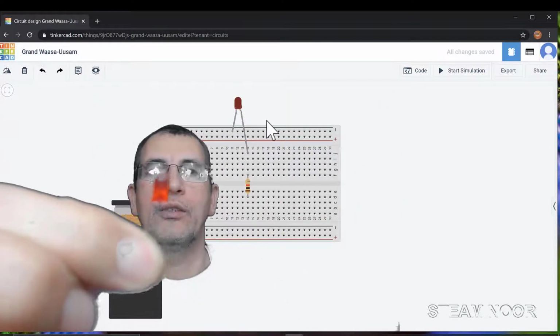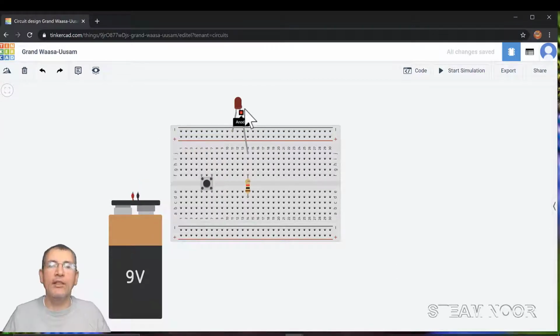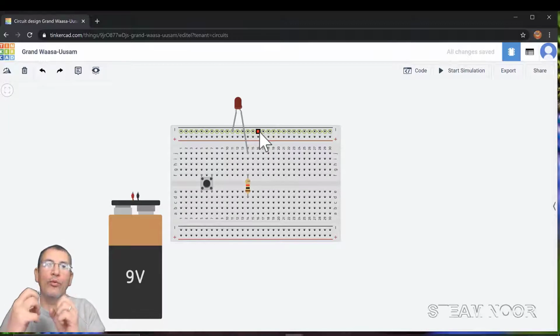This is an LED. With the LED, the way it's polarized means current will only go through in one direction. You cannot swap it. That's the role of a diode, to direct current only in one direction. So the current will flow from the positive side, go through the LED, and leave at the cathode, which is the negative side, okay. If you put the current through the other way, it's not going to go. So make sure you are using the LED right.